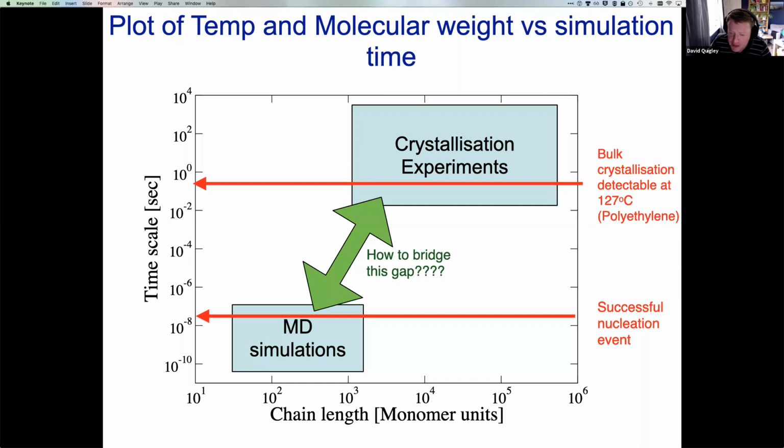So the first question was about the nucleation for unraveled polymers and whether the nucleation is driven by van der Waals interactions or by collisional processes. That's a good question. It depends on the polymer. For most typical processing polymers, it's driven by van der Waals interactions ultimately, but excluded volume is very important as well. So it depends whether you think of those as part of the van der Waals interaction. There's an attraction that joins them together, but also the excluded volume is important.